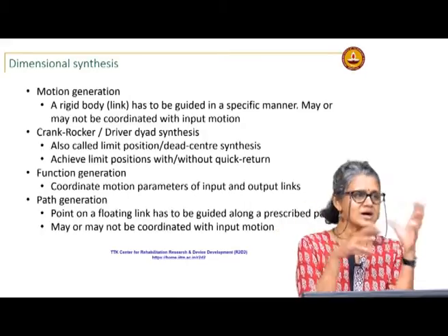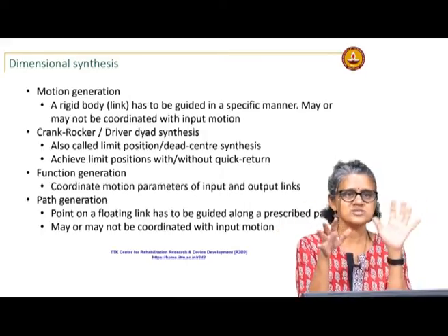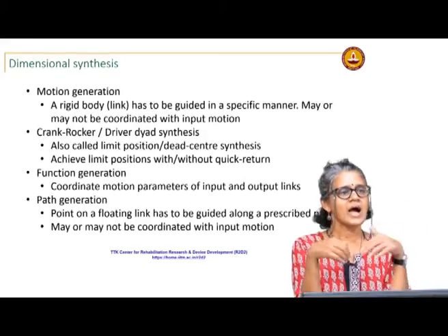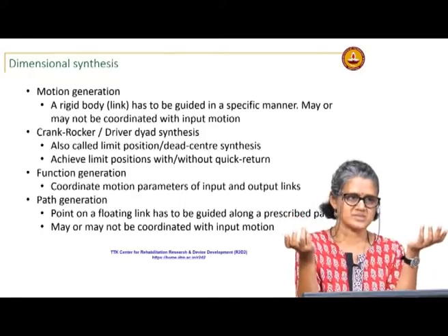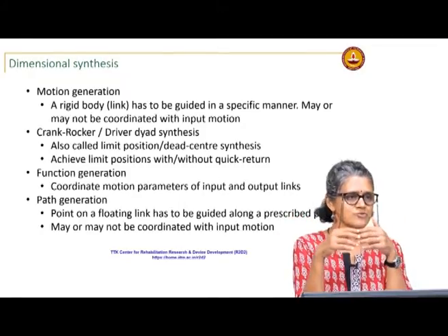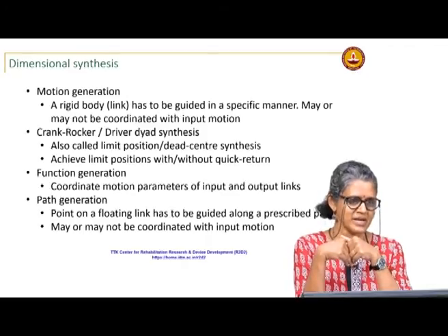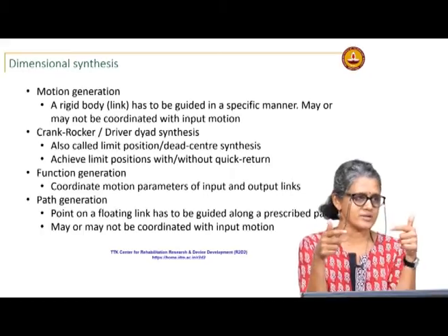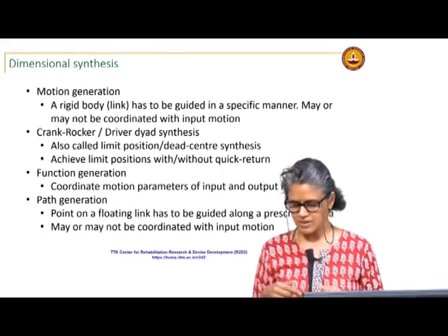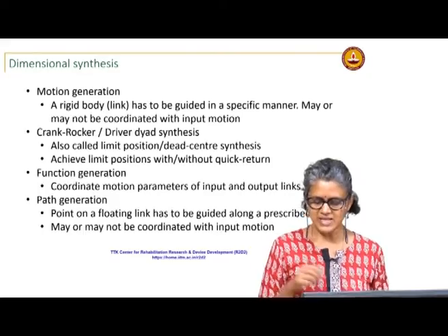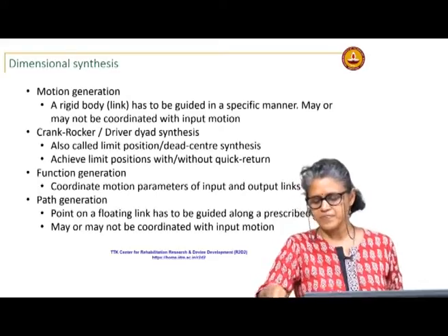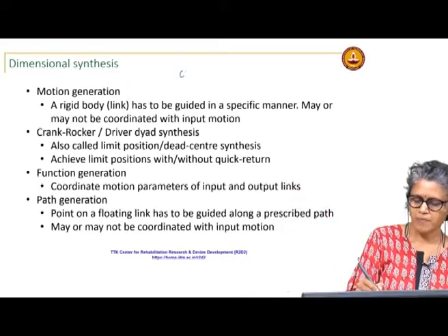The coupler will attain certain positions and orientations as the 4 bar moves, and the coupler points will trace certain paths. What you design the 4 bar for will depend on your problem classification. So, this classification is actually based on what you want for your application. That is the synthesis objective.